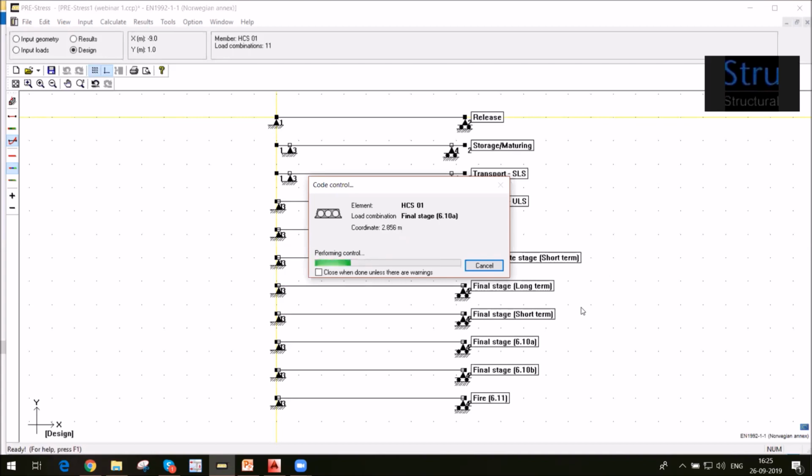You just select the category of a load for the live load, then the PSI factors are selected from the annexures which we have selected, and if you want to change them, you can do so. It gives us the default input, like okay, this will be the PSI factor for this annexure and this category. So if you want to change, you can do so. Hope I answered your query.